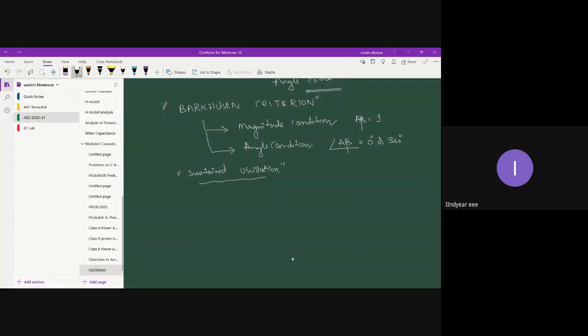In the first go, in the sense, let us say I construct an oscillator circuit with the help of an RC coupled amplifier, and I will couple some capacitors and resistors to form a feedback circuit. And I'm going to connect this circuit to an external DC power supply voltage, right? Now, the moment you turn on the oscillator circuit, the circuit draws power from DC, because it is connected to the DC power supply to drive the DC conditions in the transistor. So the moment you turn on the oscillator circuit, there exist power transients, or simply transients. Basically, the transients will drive the oscillator operation.